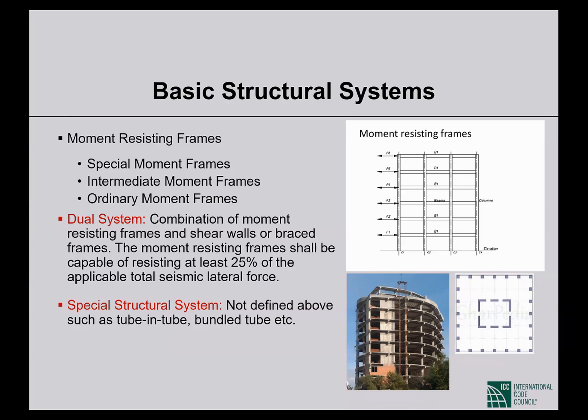These are related to detailing, that is how ductile the frame is, what amount of inelastic deformation a frame can go through. So ordinary moment frames are not very ductile. They collapse after some deformation. Intermediate moment frames are somewhat more ductile than ordinary moment frames, and special moment frames are very ductile.